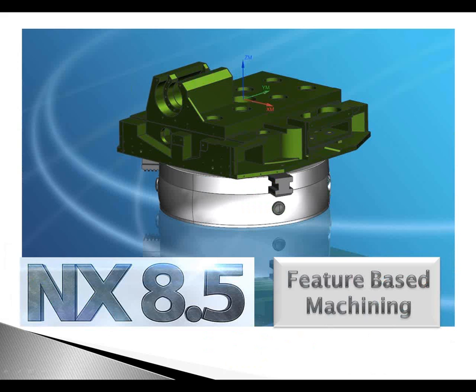Now this demo part is a typical machinery part, having many features common to any other machine part: drilled holes, tapped holes, pockets, that sort of thing. And feature-based machining is ideal for making programs automatically. We're using machining knowledge previously used to machine such features on other parts.